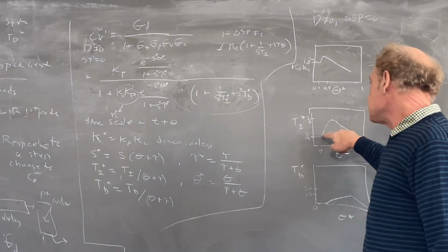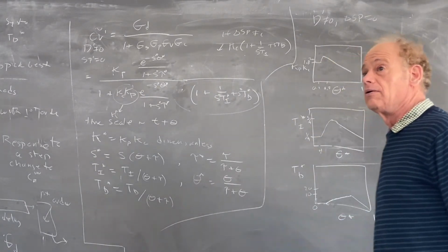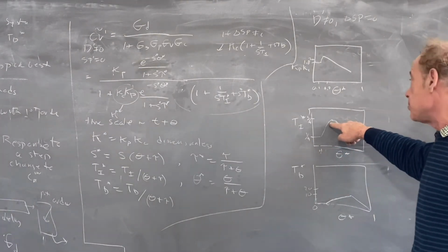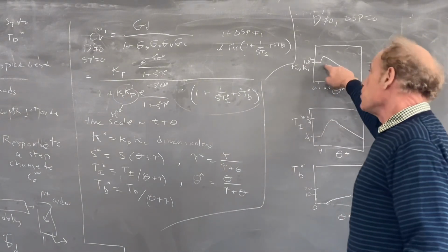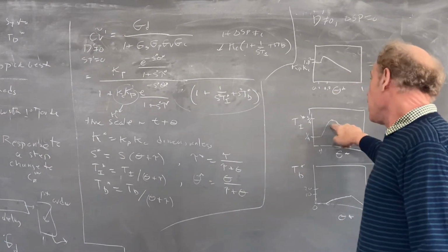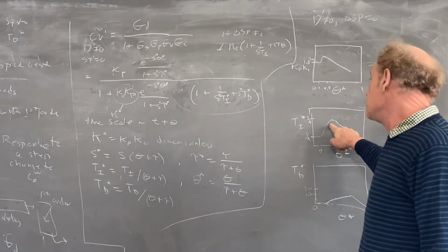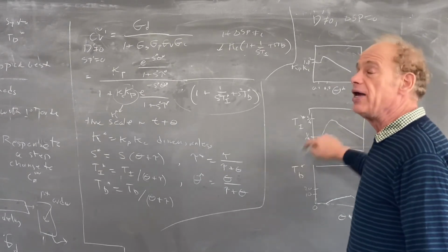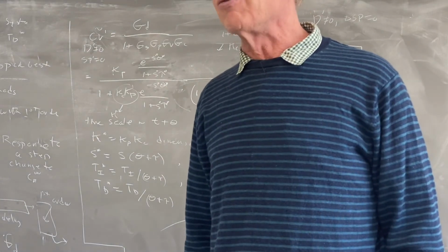So the reason this is, when the proportional controller goes on, then TI is turned on, but it's less aggressive. Because what we're doing here is we're letting the proportional controller do the work, and eventually we want to make sure that we get to no offset. So by moving up here, the integral control becomes less aggressive.